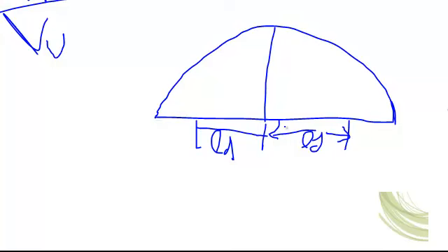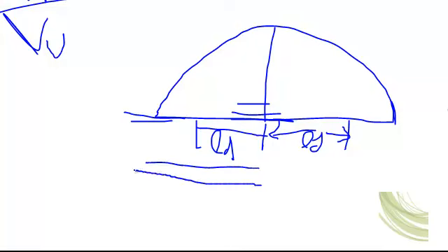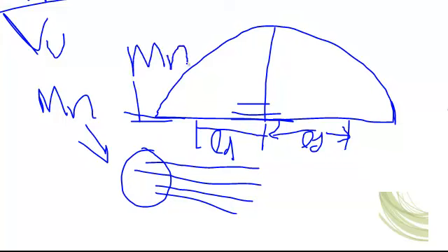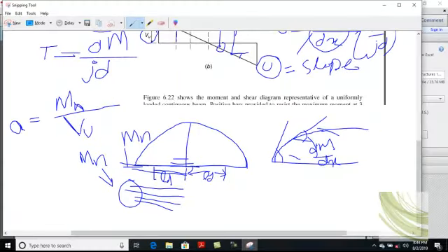So for the bars provided, for example, there may be 2 bars, or there may be 4 bars. So these 4 bars have a moment capacity Mn. If these are 2, then it has a moment capacity of Mn. So in limiting cases, these bars' development length reaches the point of inflection, not in all cases. Clear?